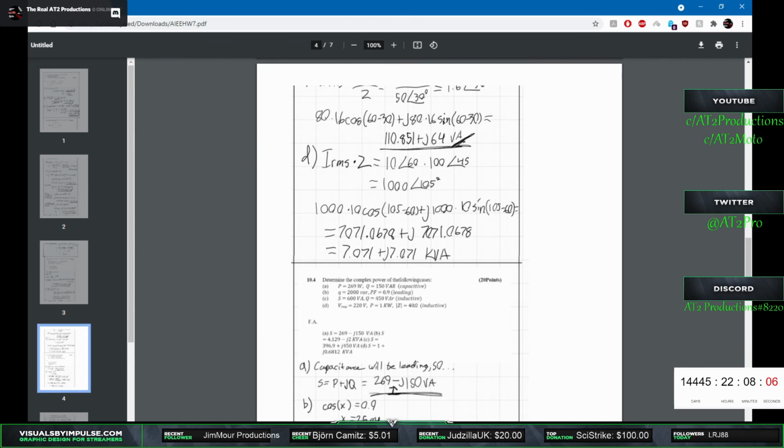Then it went into the overvoltage again and stayed there, and immediately went back into that state on power up. Disconnected the braking resistor, disconnected the motor leads, started up the drive. Worked fine, started up the way it should. No apparent damage. The motor megged fine, so there is no phase to ground short at the motor itself.